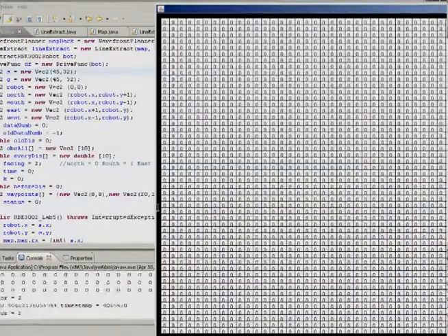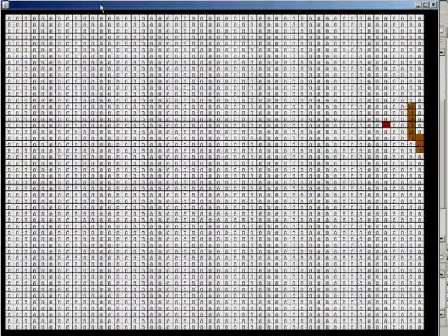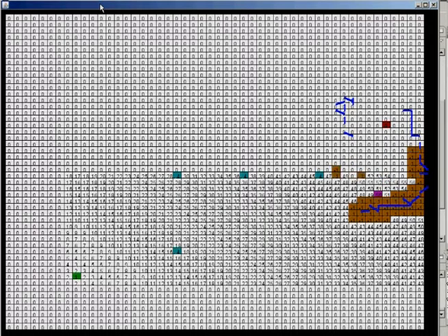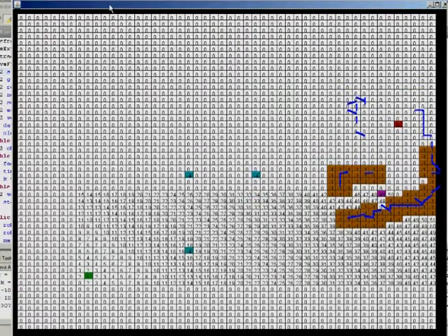For the filter, we use heavy averaging. If you are interested, we covered it in the final presentation. I believe there's a final presentation video that explains it more effectively. Also, for the actual robot, because of this filter, we need more data. So we make it 2-degree detection instead of the 10-degree detection we used in the virtual robot.